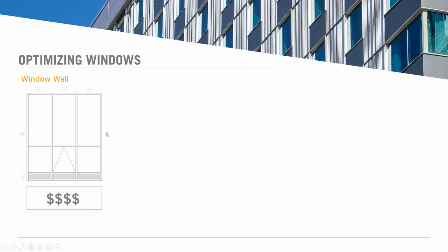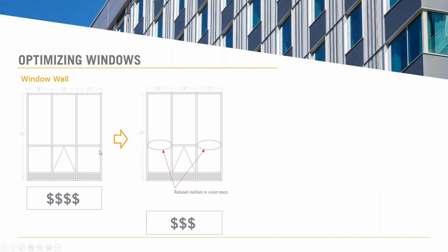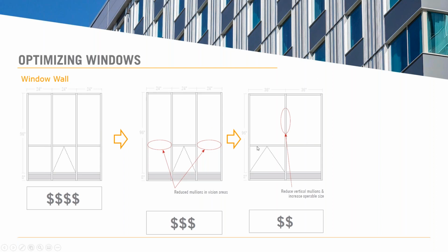Now this one is more of the same. Just wanted to point out that in a lot of designs we see a horizontal mullion at the guardrail height to try and eliminate tempering on both panes to have savings there. The best bang for your buck is going to be to eliminate the framing member in every case. The savings that you get there versus the increased cost of tempering the full height is not going to be equal. So you definitely want to focus on the mullions.